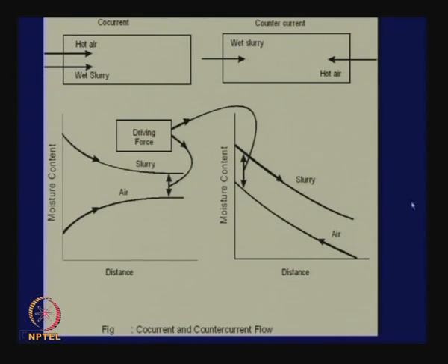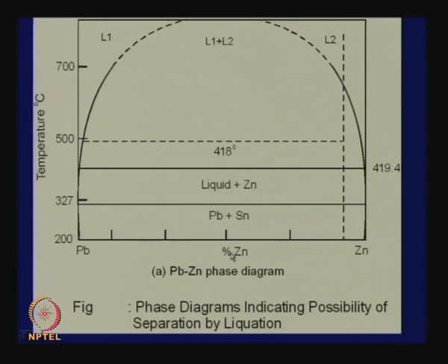On the other hand, in the counter current flow, slurry begins to lose moisture, air begins to take the moisture, and the driving force does not change. So, you can continue the process of removal of moisture over a long distance very, very effectively. So, the counter current exchange processes are very, very meaningful in the industry. Not only in the case of solvent extraction, but in many places you will find that the counter current flow concept is made use of.